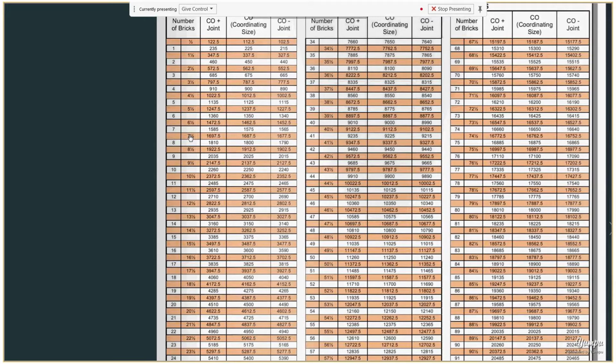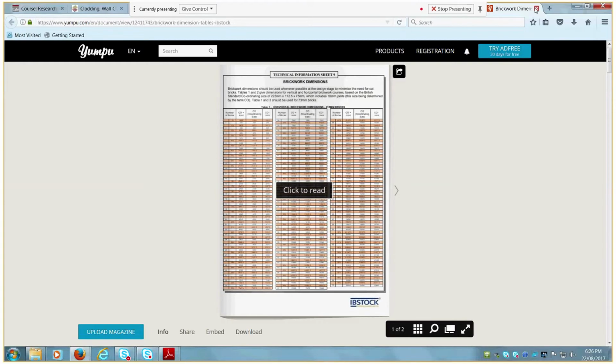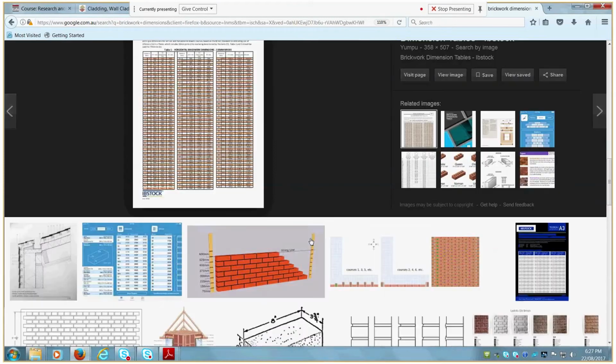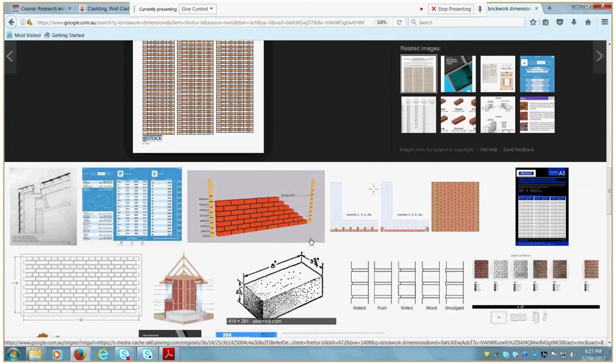So if your horizontal joint is 6 bricks in, plus joint, it's 1360, etc. The placement of your windows, or any opening in the brickwork, should be done in accordance with those brickwork dimensions. Even your wall lengths, exactly. You don't want to cut bricks.